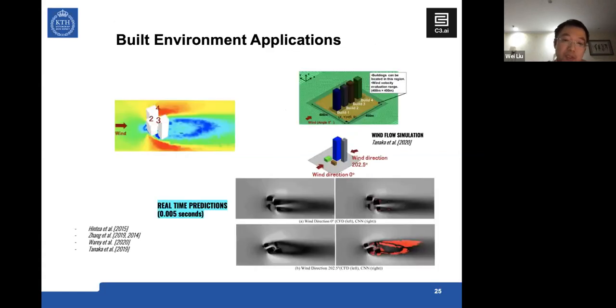When upgrading the scale of simulations from indoor to the external environment, like urban cities, accuracy deterioration and difficulties in considering complex boundary conditions, such as the weather, are inevitable. In this study, they conducted urban flow simulations where the location, dimension, and shape of four tall buildings were optimized in a restricted area with the construction of a CFD optimization tool. The objective is to reduce the wind forces on buildings and mitigate local strong winds at the pedestrian level.